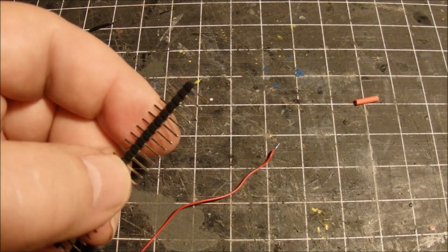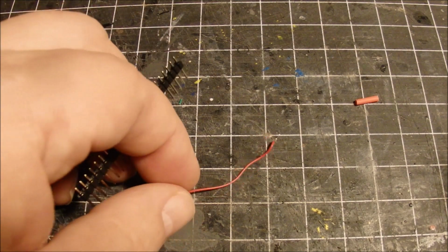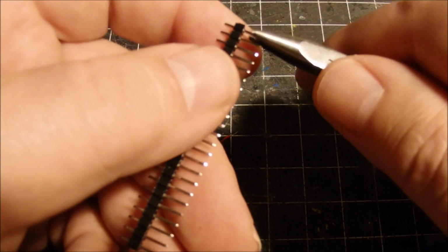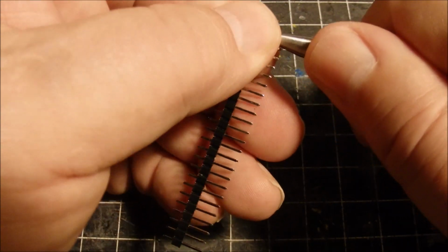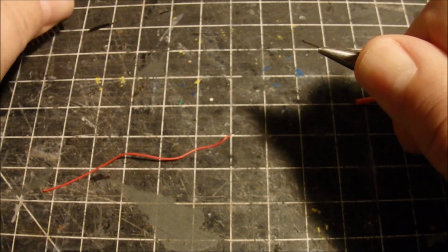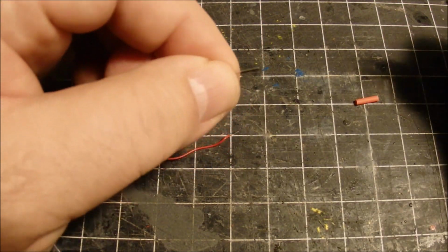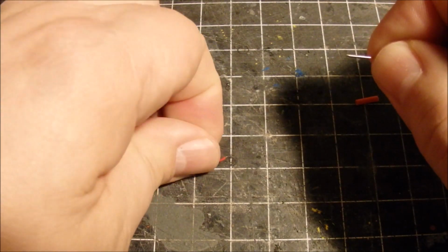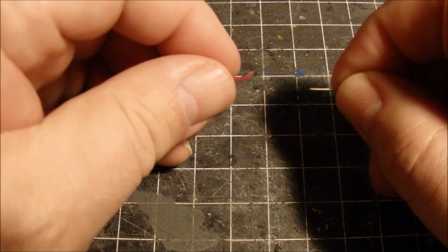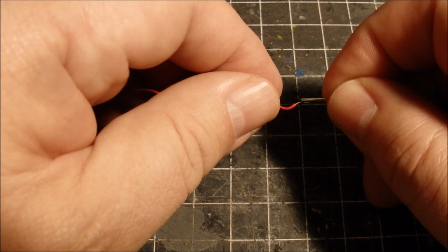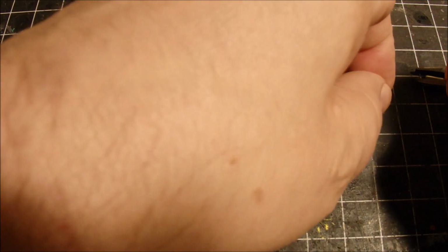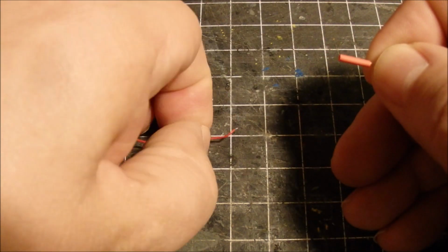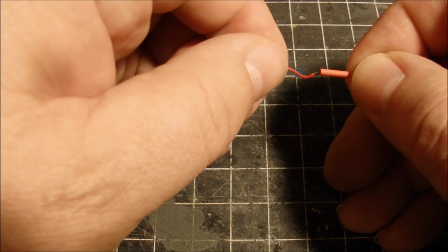Another little trick I did for all the wires coming off the LEDs, they're very fine wires. What I do is I take a little pin right out of these slots here. Now I've got just a separate pin, and I used a little bit of solder, and I'd solder my LED wire right to that pin, and then just use a little shrink tubing around that, so you get a little connection that looks something like that.